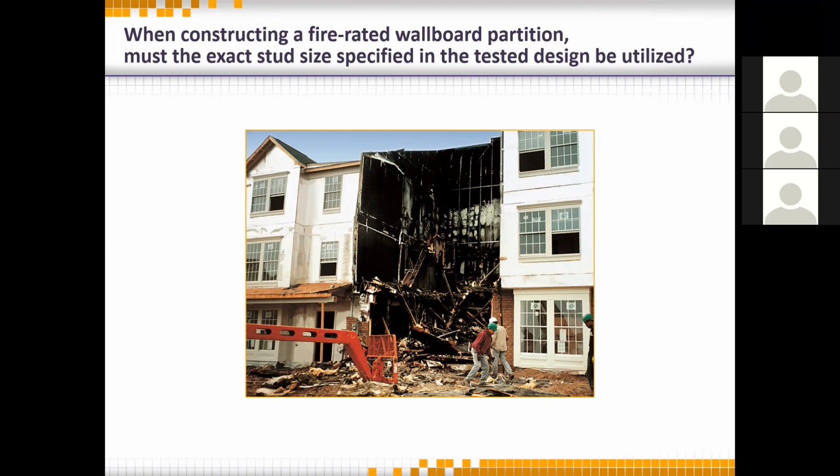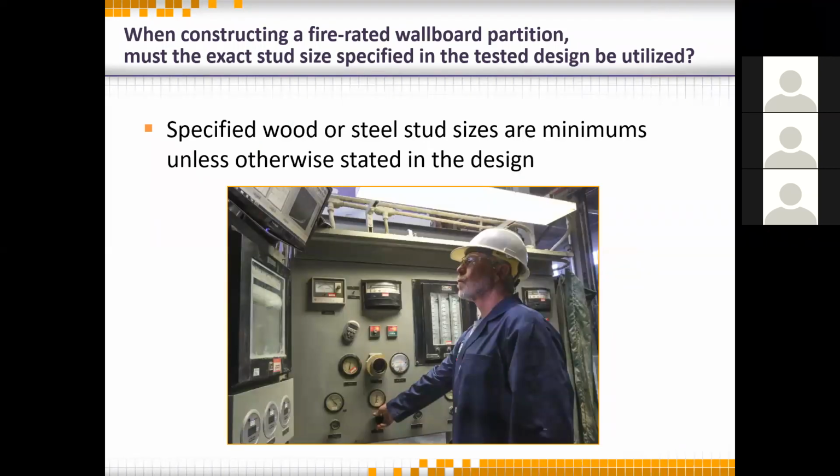The metal system is attached to the stick framing with aluminum clips, lots of them. As they get hot and melt and give way, the stick framing falls on itself, fire goes out. So it's a great system to use to protect, obviously, adjacent units. Lots of different parts of the country are using this system. So good system. Anyway, back to our studs. Remember, studs is a minimum unless it's otherwise stated in the design. So we've got to read.